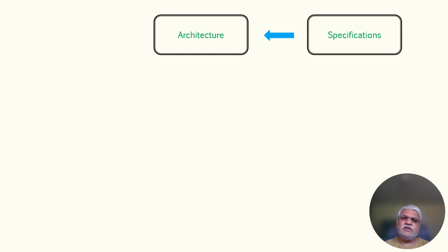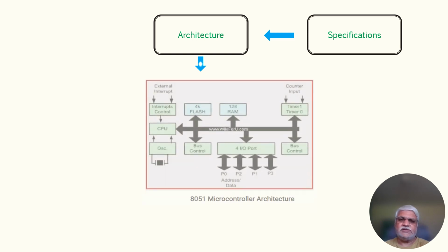As we observed in the earlier video, system design specified in the requirements and specification stage is translated into architectural design as part of the design making to bring more concreteness. The architectural design is then converted into RTL design to give more specificness of the design implementation. Briefly, RTL design allows the designer to describe the system in a way that is independent of the specific hardware that will be used to implement the system at a later stage. Thus, RTL design is said to be grossly process technology independent.